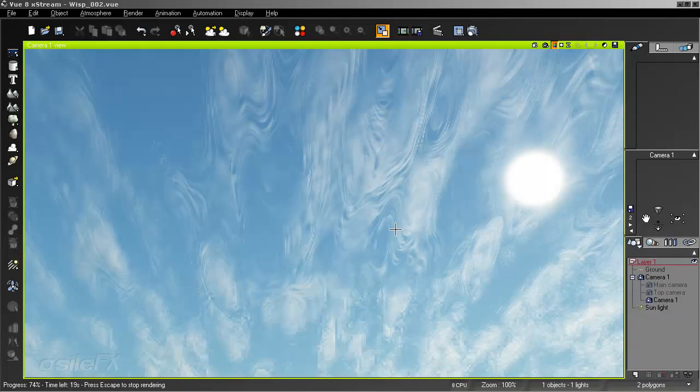And this is still rendering out, so it's a little pixelated. But it gives you a good idea of what it's going to look like. Now I am using noise nodes just to cut down on rendering time. If you want to have something broken up a little bit more and the detail settings aren't really giving you what you want or the look that you want, you can change the noises over to fractal.